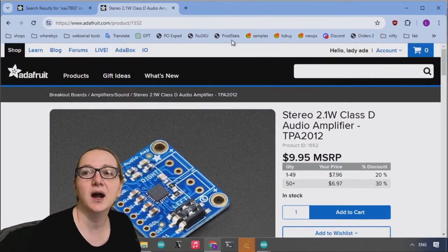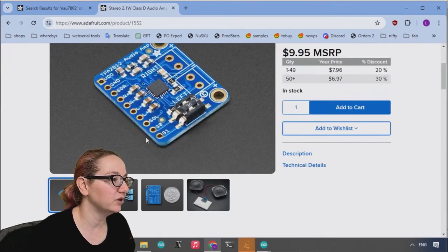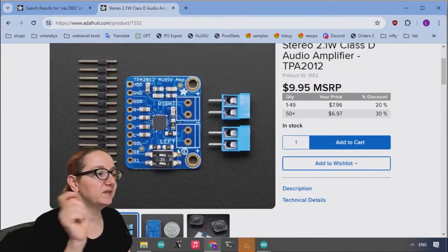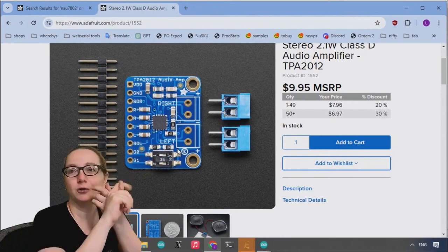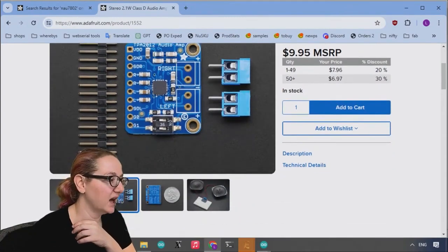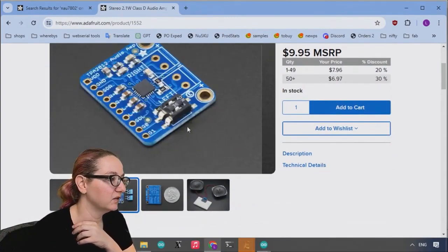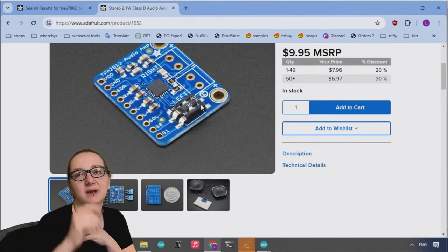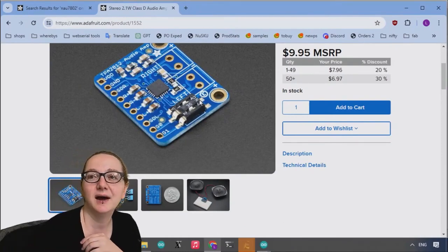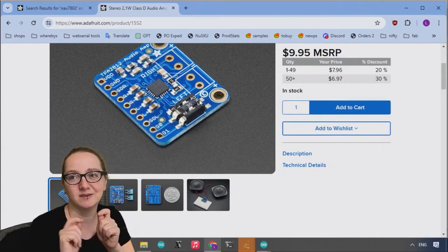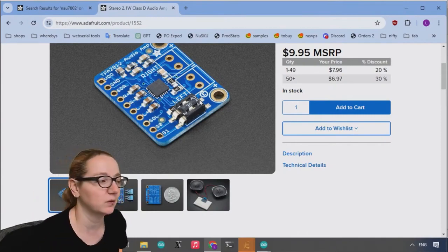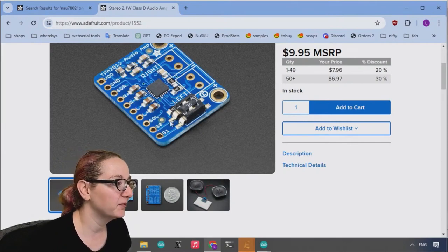Here you go. So on the TPA211, to set the gain, this is like a later design. I was like, oh, I'm going to use a dip switch. And so you can set the 2 bits of the gain by flipping the switch. And what's nice is you don't lose the little handle. It's a lot slimmer. So you can see it doesn't rise up more than like a couple millimeters. Of course you can set both at the same time. That's the only thing, is make sure that your design doesn't break if people flip 2 switches at once. So I prefer these now.